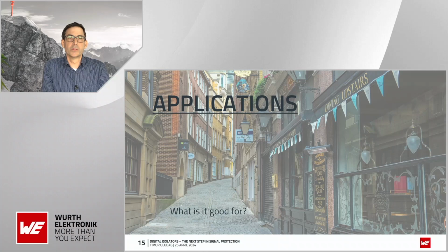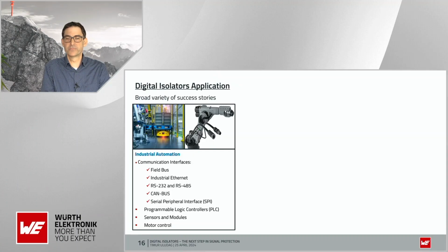So now we know why we need a digital isolator. We now know how it is working. We know how it is built up. Let's check out a little bit more what applications are standard for a digital isolator. First of all, industrial automation. Here we have a lot of RS-232, RS-485, CAN buses, so standard industrial buses that we can protect with a digital isolator.